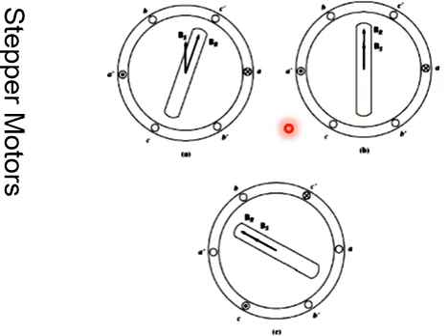Similarly, in another case where A and B windings have 0 and C has minus VDC voltage, then this would be the direction of BS and BR. So this is 60 degrees shifted from the previous case.